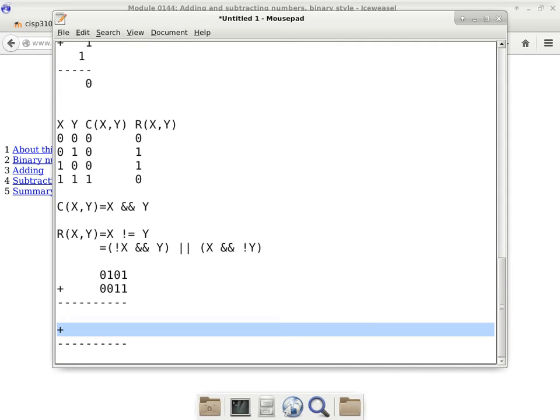Okay. Well, if that row represents carries, what about this row here? This row is only representing the actual result of adding the input, the 2 numbers. So 1 plus 1, the result goes here. The carry goes here. Let me go very slowly so that you know what we are dealing with here. Well, since this row is all about the carry, what should I put here? 0. It's a 0 because there are no previous digits. This is already the least significant digit, so there's nothing to carry into this particular digit.